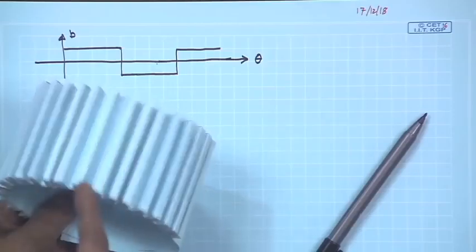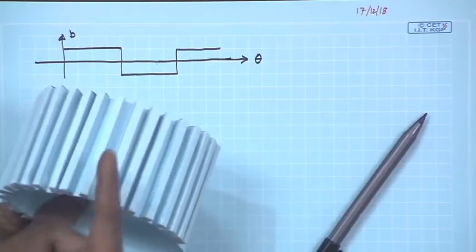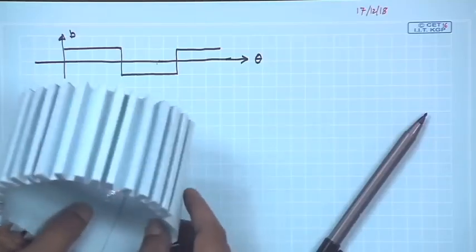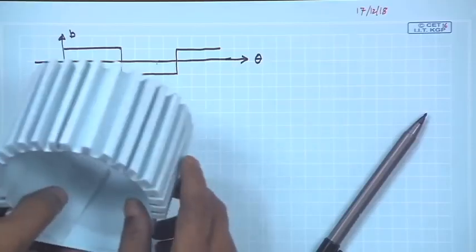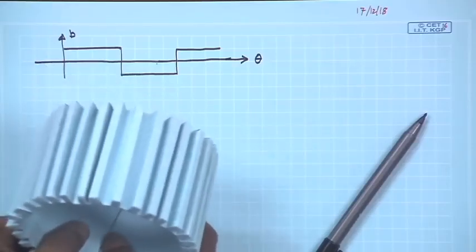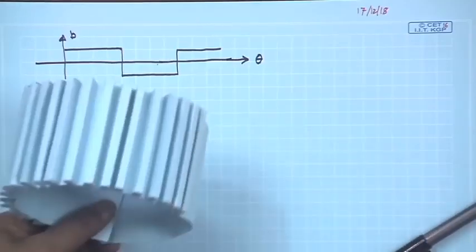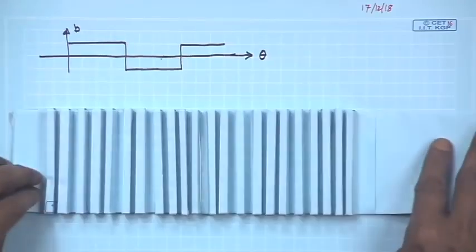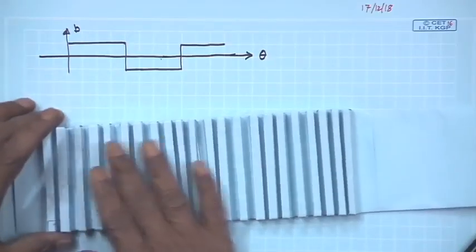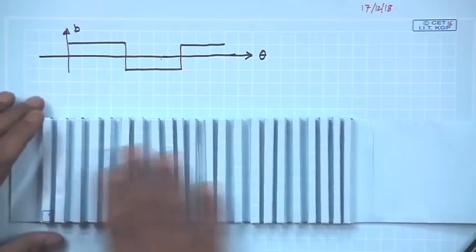As I told you, we will cut slots, and in these grooves or slots I will place conductors, and these things will be rotating. Therefore, as I told you, I will cut it open for understanding and display it like this. So, it becomes a sort of linear way of understanding a rotating electrical machine, that is called the developed diagram.